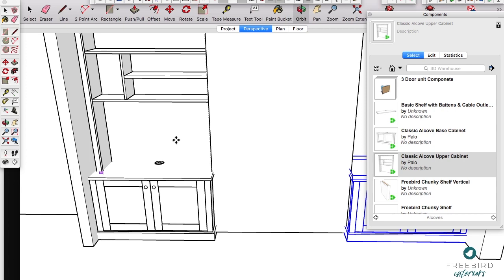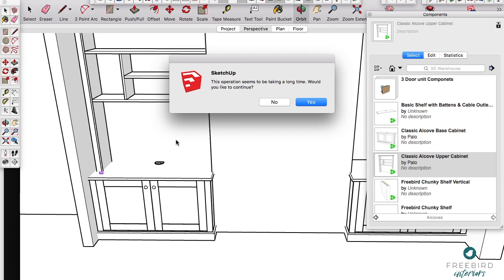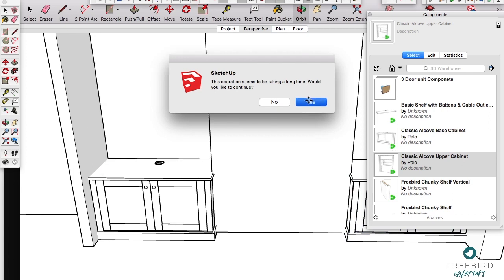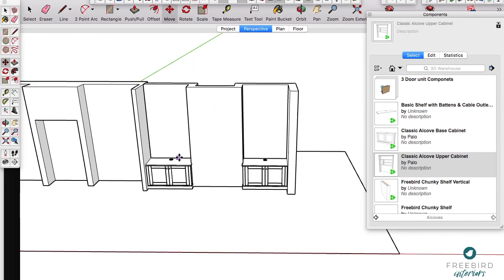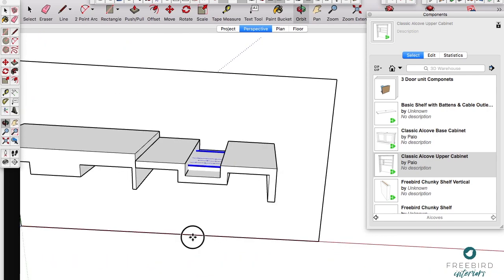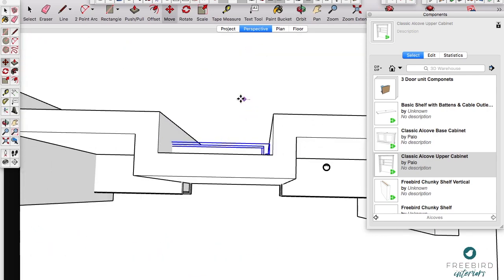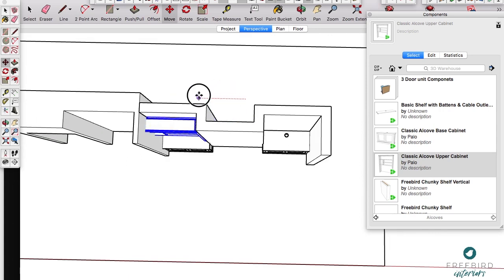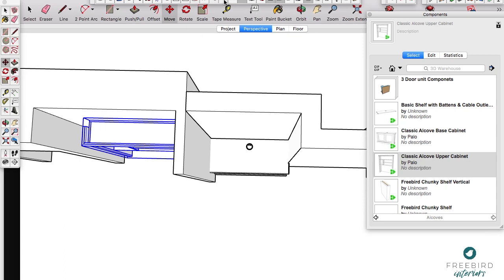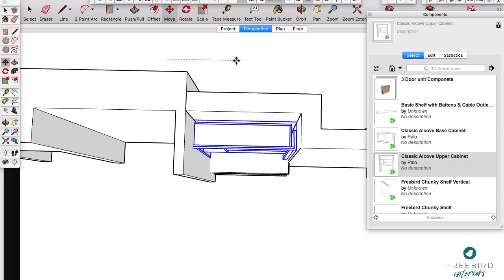And something to say as well is that with the cabinet sense walls that I drew on this side of the model, they interact with the cabinet sense components, so the components will drop in at a set distance from the wall, so I can set a rear void and things like that. Right, this is a problem I sometimes have, is they sort of find the wrong wall and want to snap somewhere else that I don't want them to go because they're being a bit too clever, so I can then turn a line off.